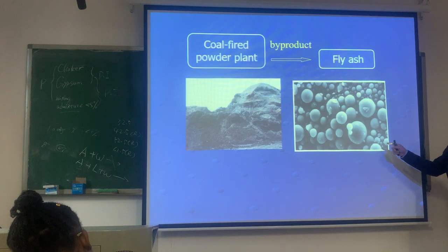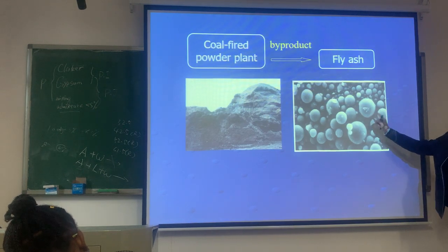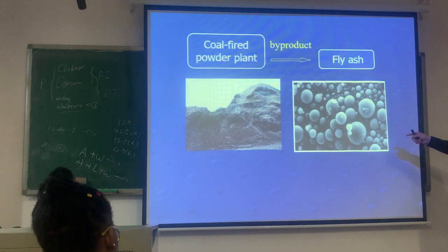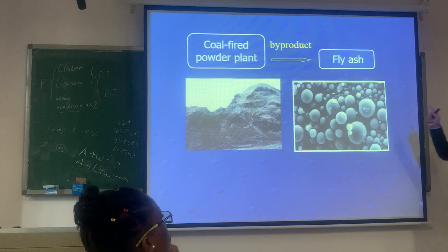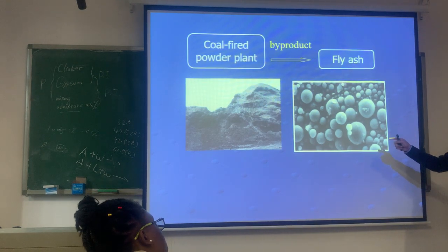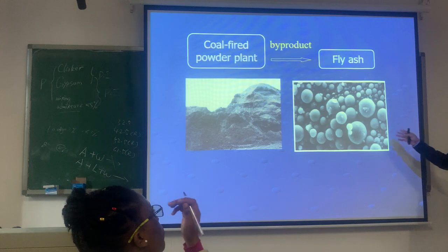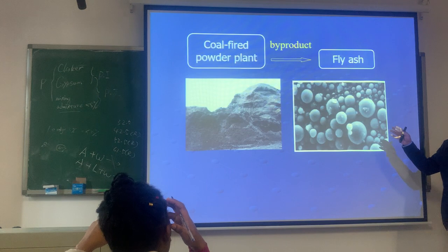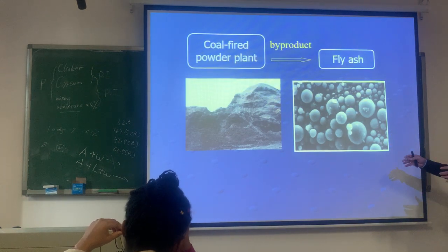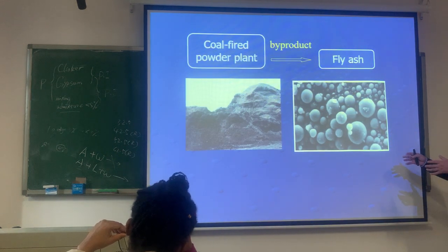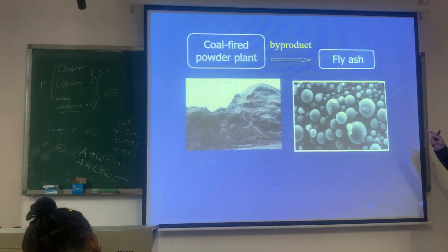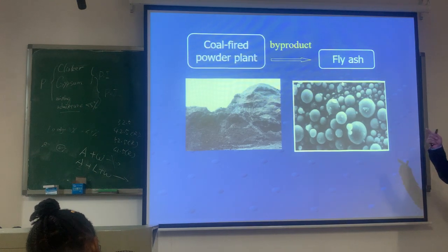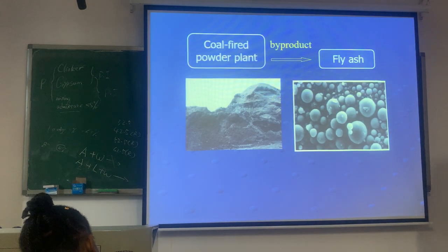And then another reason, because it is a kind of active mineral admixture. What is an active mineral admixture? It means it can react with the water and lime to get cementitious products. So it is good for the strength, especially the late age strength of concrete or cement.